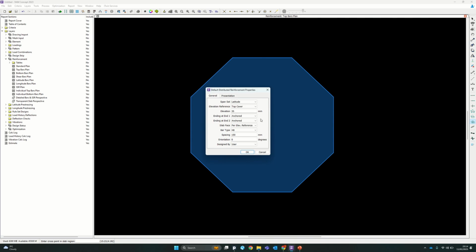Yeah, if you're doing advanced detailing where you're trying to work out whether the bars have got enough anchorage, if they're lapping around corners and stuff, I probably wouldn't recommend that, but for most of the cases that I've used, I find this is useful enough. So yeah, I'll go ahead with this bar type.